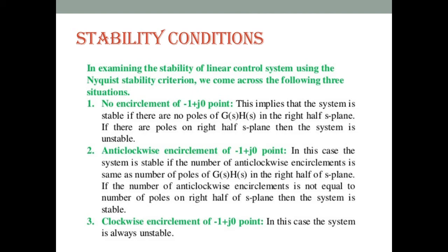So in the clockwise direction, if the s-plane contour encircles more zeros, that is Z is greater than P, in the clockwise direction, then the Q(s) plane will encircle the origin N times in the clockwise direction. And in other words, if the contour in the s-plane encircles more zeros than the poles of the Q(s) or F(s) in the counterclockwise direction, then the corresponding locus will map in the Q(s) plane, which will encircle the origin N times in the counterclockwise or anticlockwise direction.